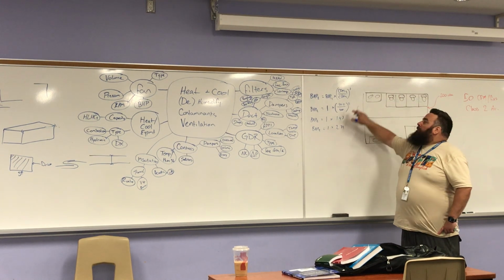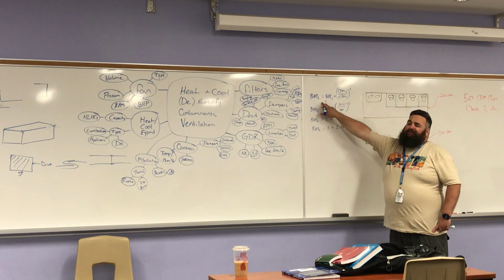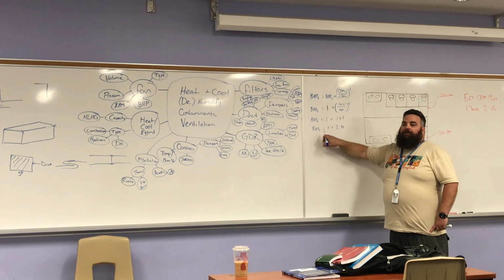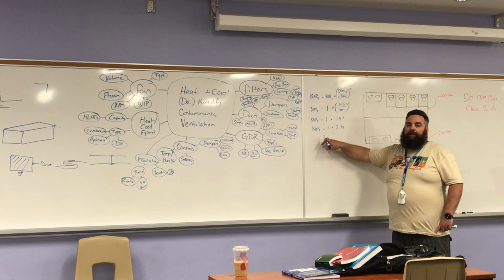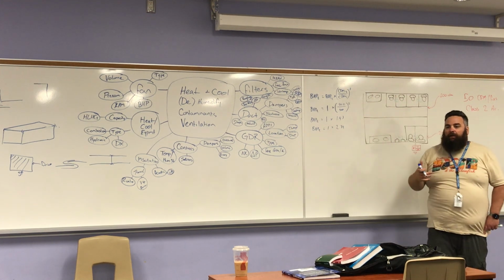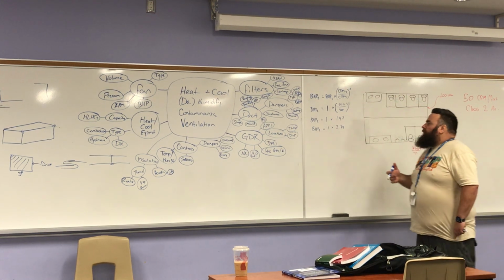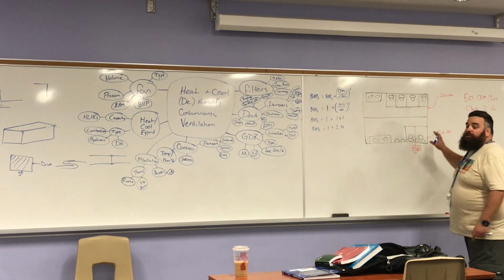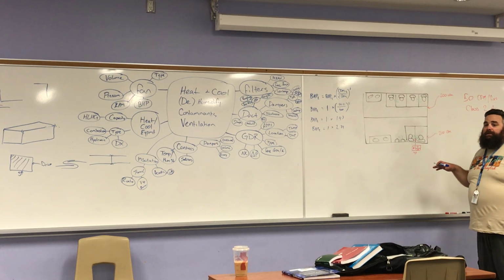Okay? My starting brake horsepower was going to be fairly low to begin with, so it's not the end of the world, but there is a very real consequence here for doing that. That's why it's important to understand our fan laws. Okay? So we can know that these changes might result in something that's undesirable.